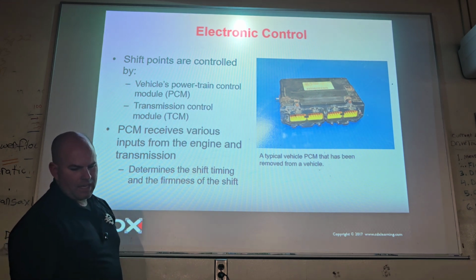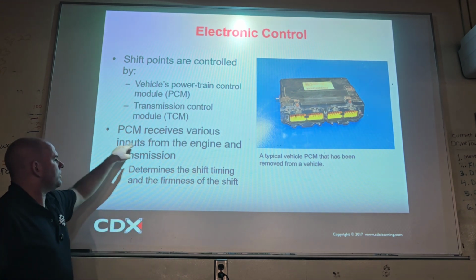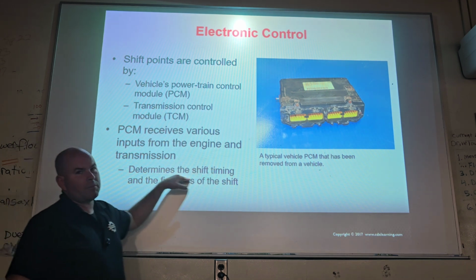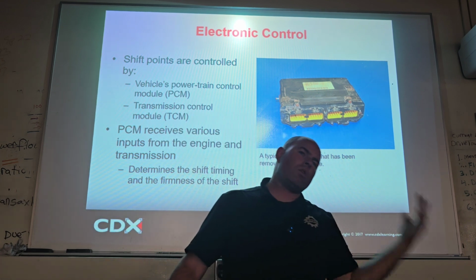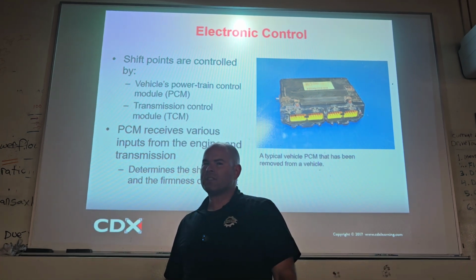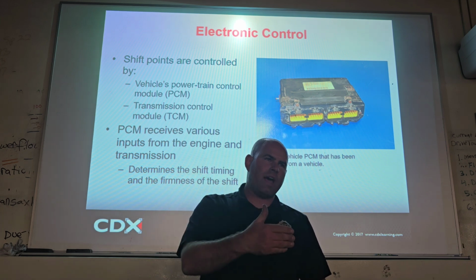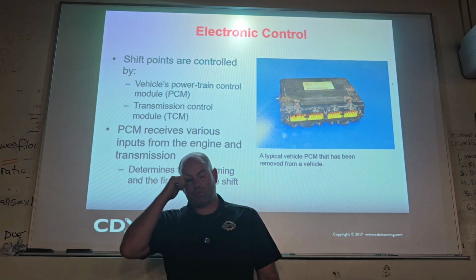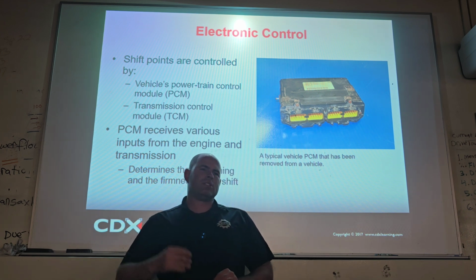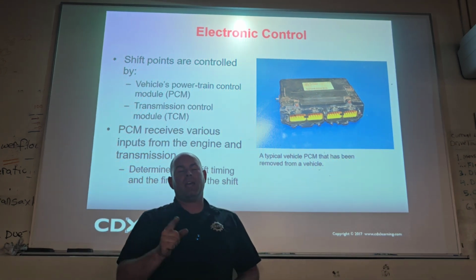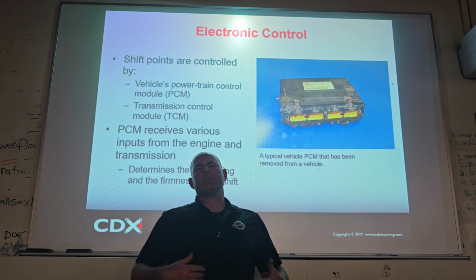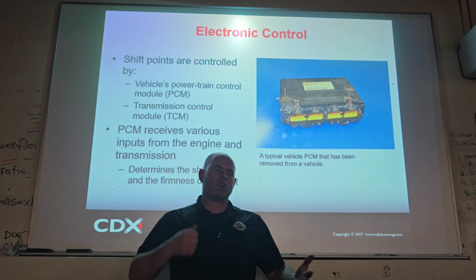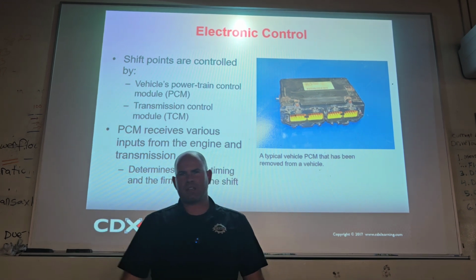Right? And then again, it's receiving inputs. It is determining the shift timing and the firmness of the shift based on its programming, and then it will execute a task. So if you're at wide open throttle, it sees that and says, okay, hold off on the shifts, let's delay them till near red line, and let's firm it up. Let's ramp up line pressure. It'll increase line pressure right there on the spot, and then you'll get late firm shifts. Boom. Chirping gears, banging gears, pretty cool.